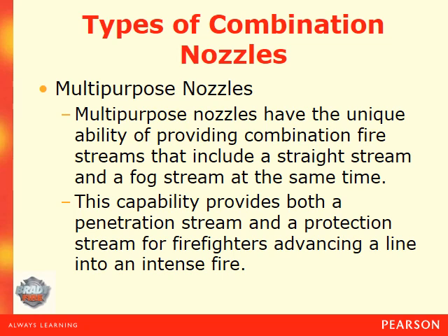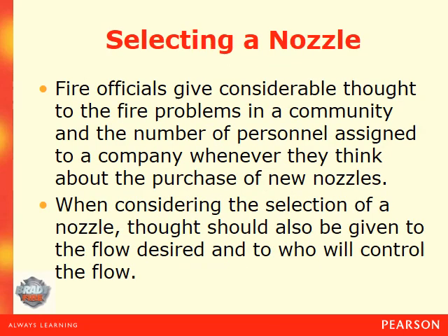Multi-purpose nozzles. Multi-purpose nozzles have the unique ability of providing combination fire streams that include a straight and a fog stream at the same time. This capability provides both penetration streams and a protective stream for firefighters advancing a line into an intense fire.